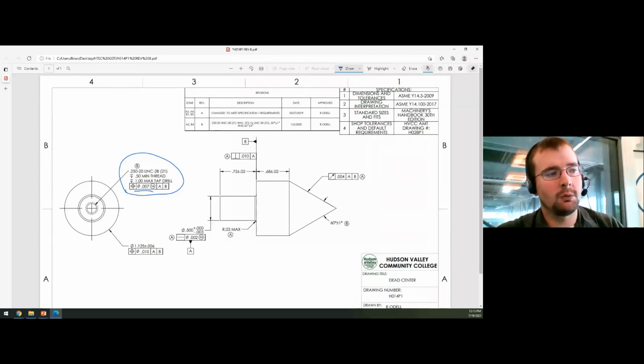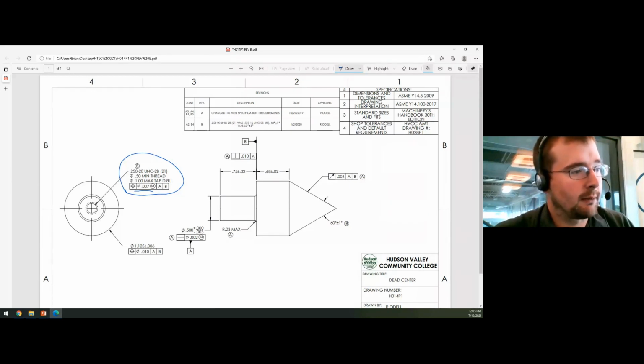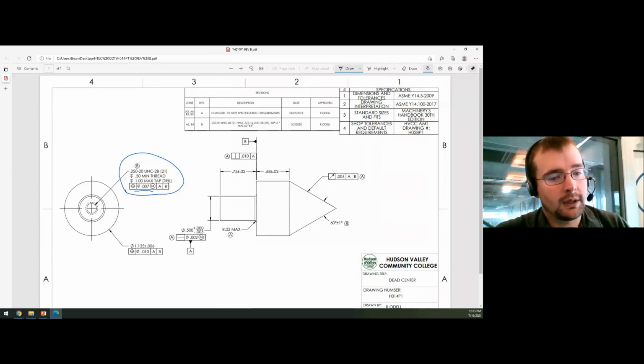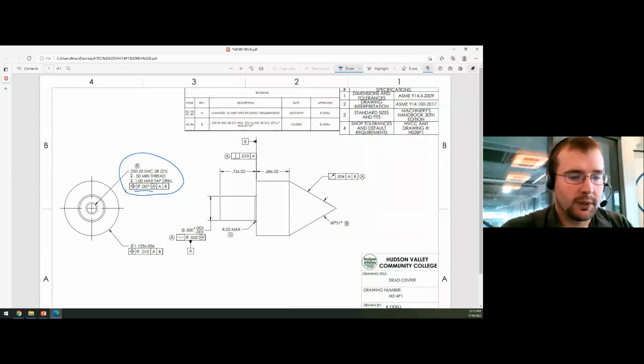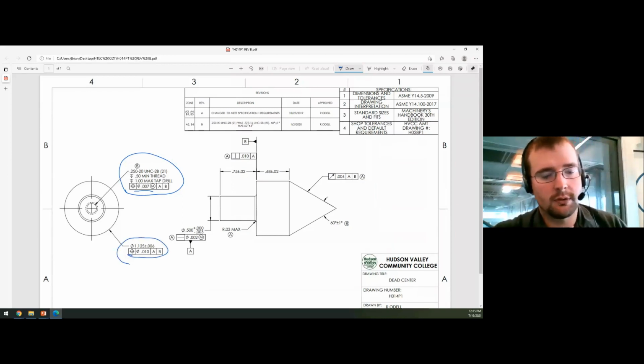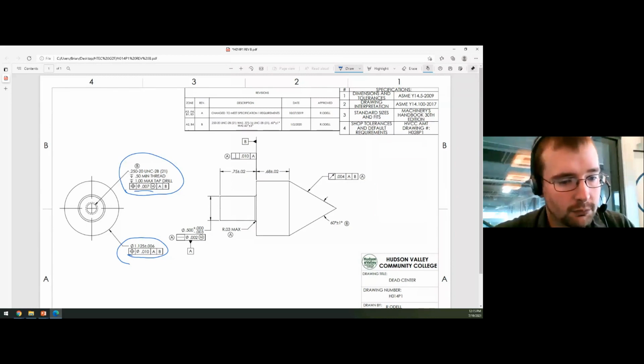Can you get away with it? What it means, because to the engineer, it may not matter, but to the machining operation, to check to the pitch diameter can be tricky. Okay, so that's just one example. We talk about in this application, this is true position versus, it could be runout, total runout, circular runout. Why is this true position? Why is this runout from a design standpoint?